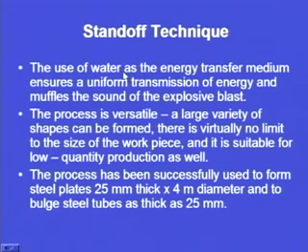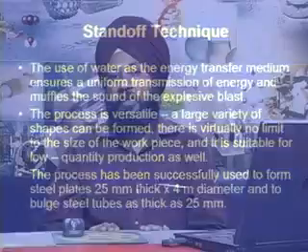The use of water as the energy transfer medium ensures the uniform transmission of energy. So, we have seen a pressure pulse that is generated, and a uniform transmission of energy is ensured if we are doing it underwater. It also muffles the sound of the explosive blast. So, if we are doing it underwater, there will not be a loud sound, or we can say that pollution because of sound may not be there.